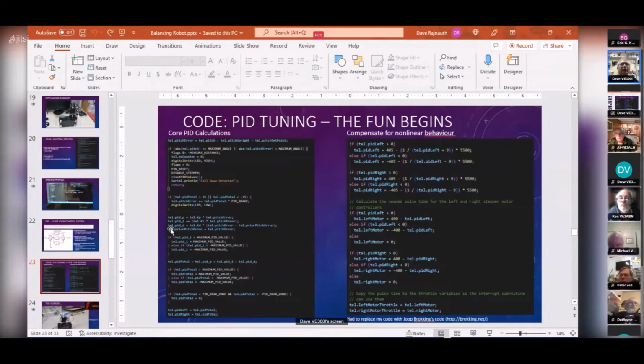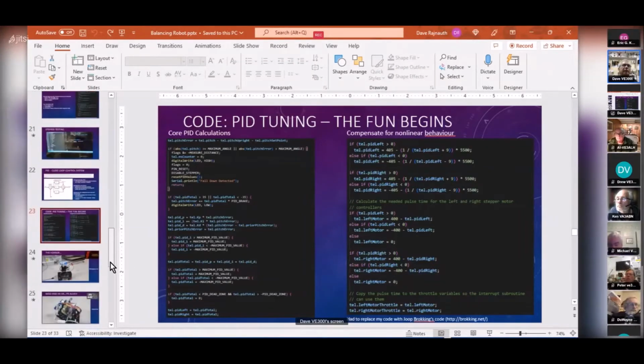And the D term is just the derivative, the difference between the two terms. And here's my sum. I calculate my PID and feed it in here, and this then figures out the pulse frequency that I need to send to that 20 microsecond interrupt. So enough said about that.